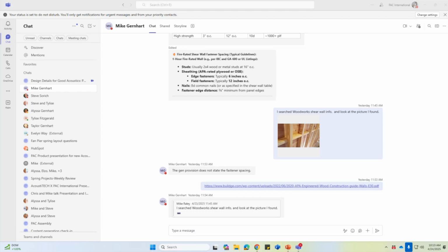Right, right. And yeah, the point is that they're separated. There's not this continuous structural path. So again, if you're looking at your drawings, say, can you trace a line that's got this continuous structural path all the way across? And if you can, that's an issue, and you usually need to try and figure out something different.